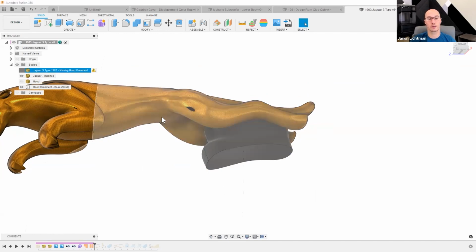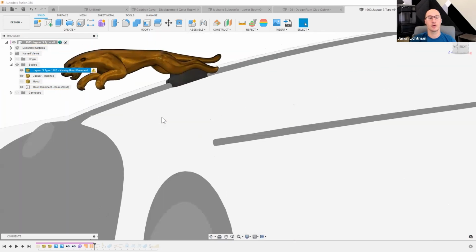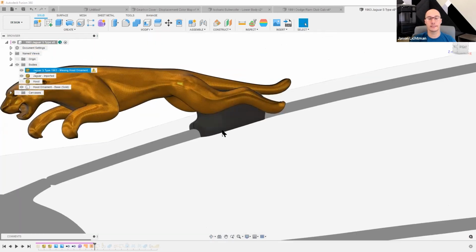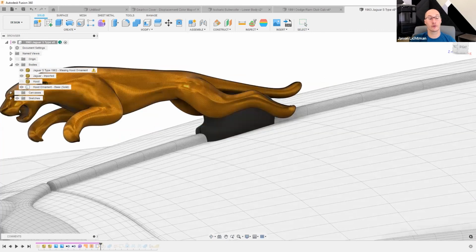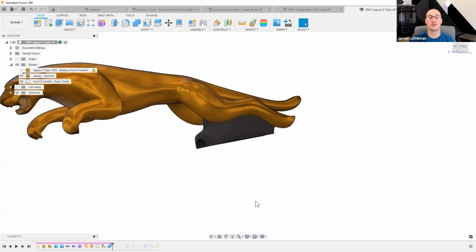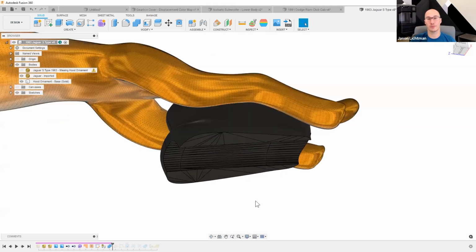So the hood of the vehicle, well, I have to change my view there. The hood of the vehicle is interfering, so we want a nice, good fit. I can also convert the hood into a solid, just like you can see here, and then use a Boolean cut as a solid to be able to chop the hood away from this organic base shape.